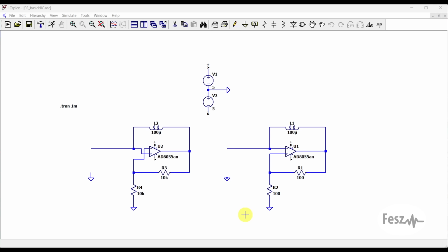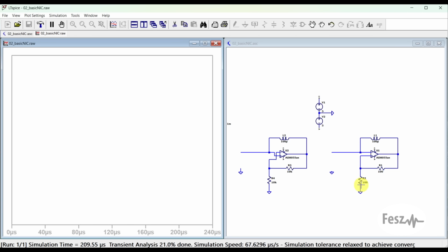Or do they? Well, the AC simulation seems to be just right, but that is not the only type of simulation that you can perform. Just to be on the safe side, I took the same circuits, removed the injection source, and ran a transient simulation, just to see the time domain behavior. So the expectation here is that since there's no injected signal, the negative impedance converter has nothing to react to, so the input should be at 0.